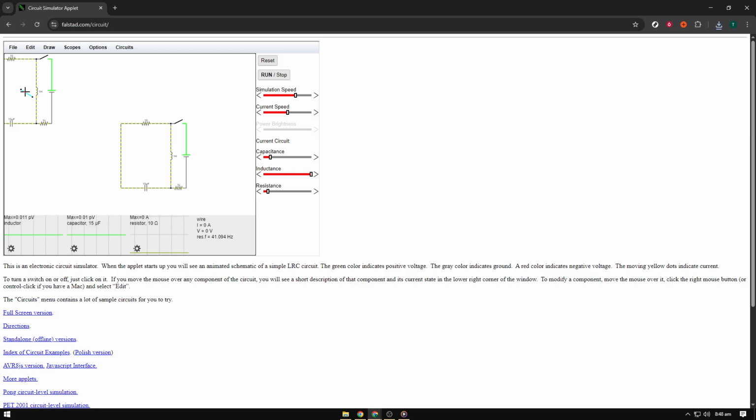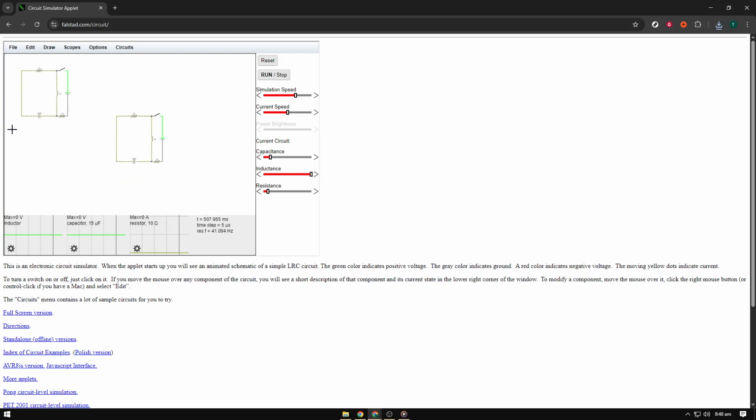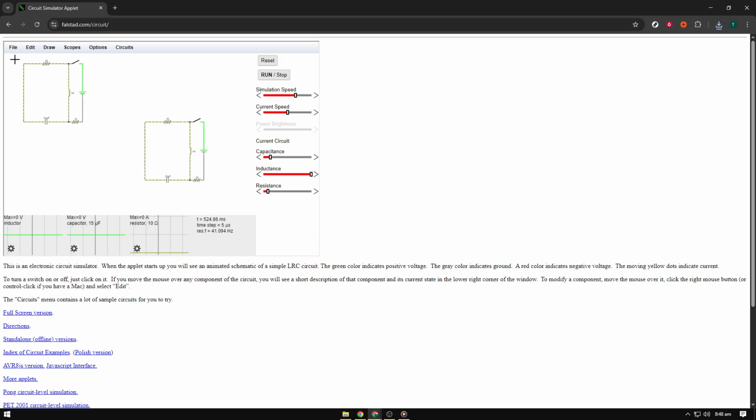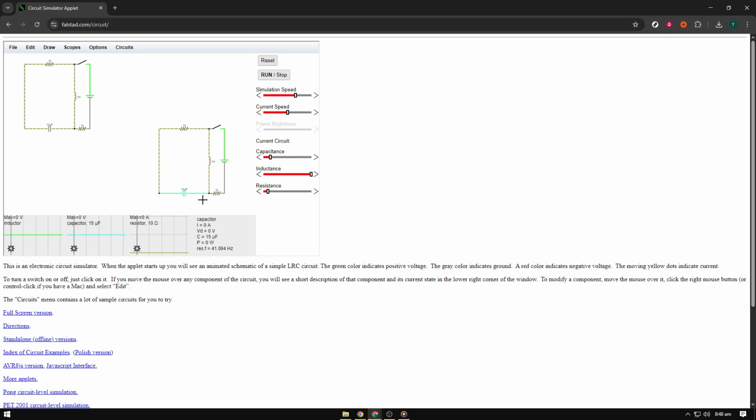Once you've positioned the duplicate, give it a quick visual check. Confirm that the entire subcircuit came over: all the components, the connecting wires, and the junctions you expected. Look for any places where wires might unintentionally touch existing lines, and make sure the duplicate sits where it won't be confused with the original. A careful placement now will prevent connection errors later in your design process.